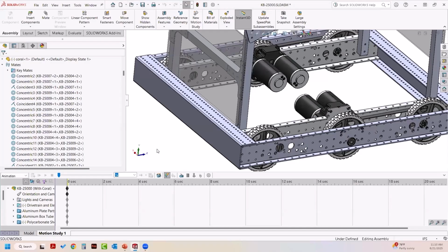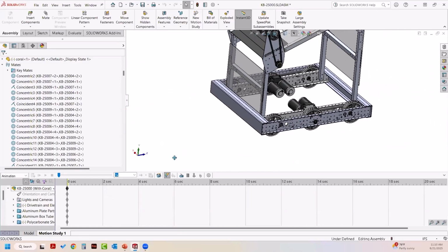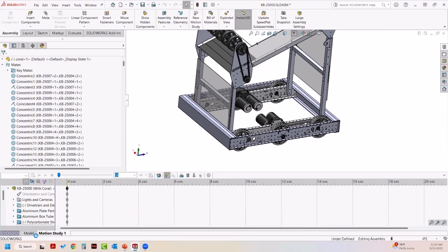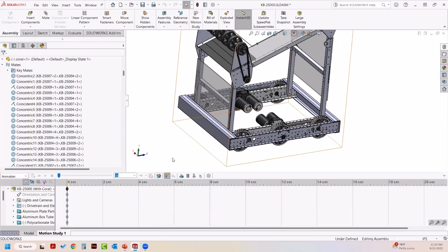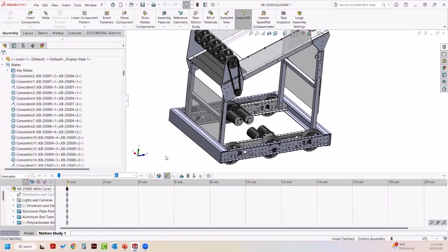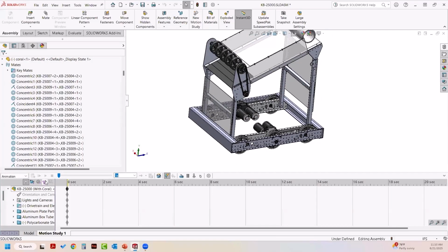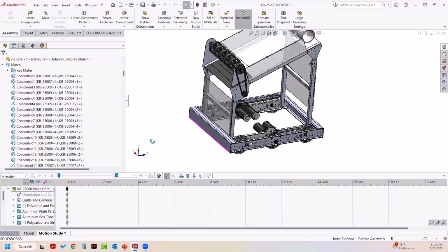Now, I don't really want to have this reoccurring as I'm setting my study up. So I'm going to turn off this feature by right-clicking orientation and clicking disable playback of view keys. And now I can move this around and switch between the tabs, and I'm not going to get that warning message appearing again.